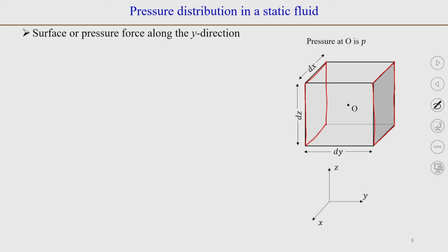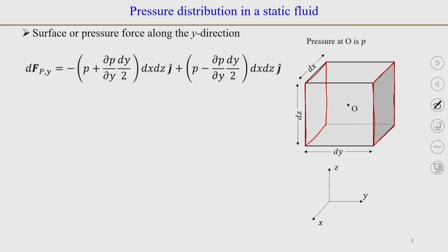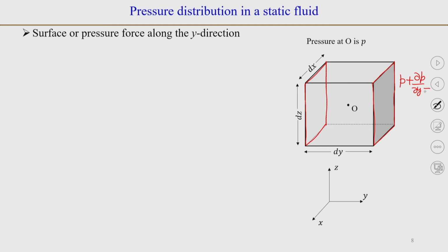So, let us look at the pressure force along the y direction. If we look at the surface on the right, the pressure here is P plus del P over del y dy by 2, and the area of this surface will be dz into dx.